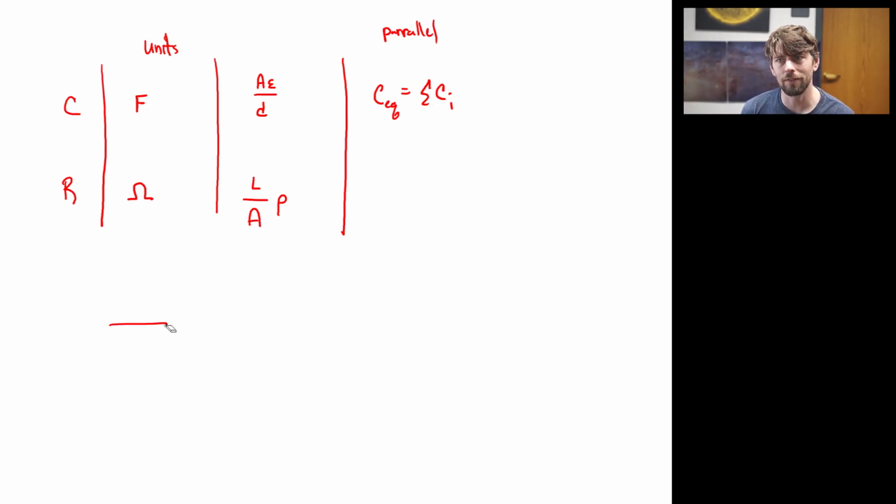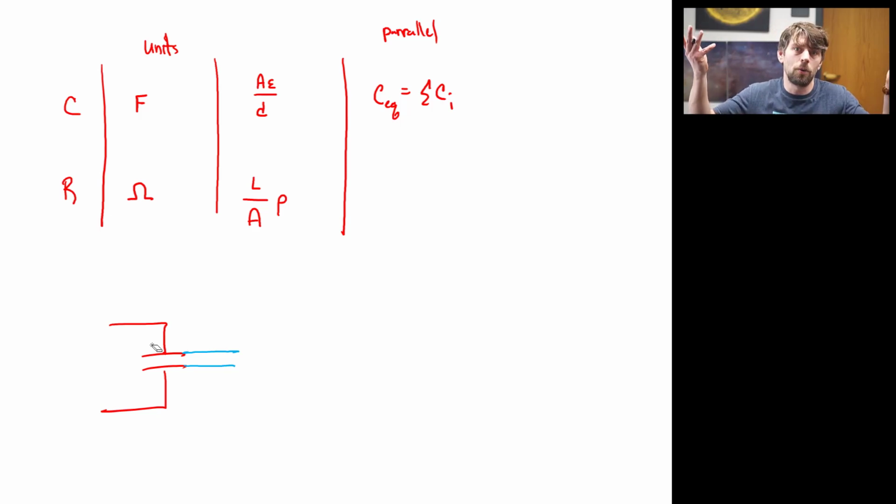In some sense, I think of it literally as, for example, if I have one capacitor and I have a second capacitor, well, let me just shorten these two wires. I'll make this wire shorter, I'll make that wire shorter, so that those two plates just end up coming in contact with one another, right? Like okay, let me do it in blue just so we can distinguish. I'll just make these lines really, really short so that those two capacitor plates are essentially touching. And you could conceptualize that as I've made the area bigger. And because the area of the plates is now bigger, the capacitance should go up.